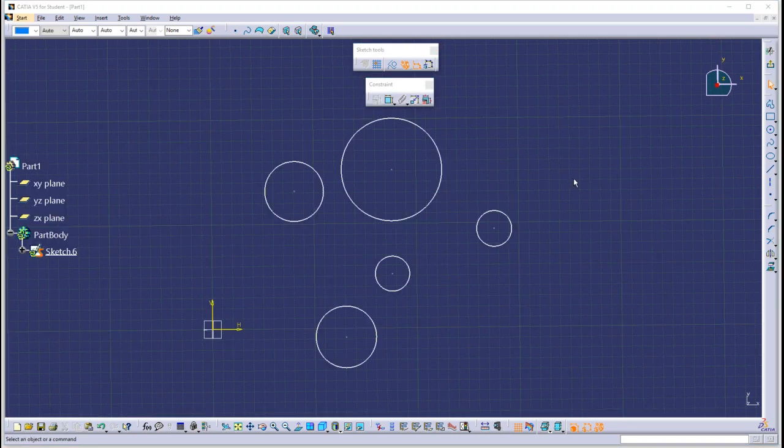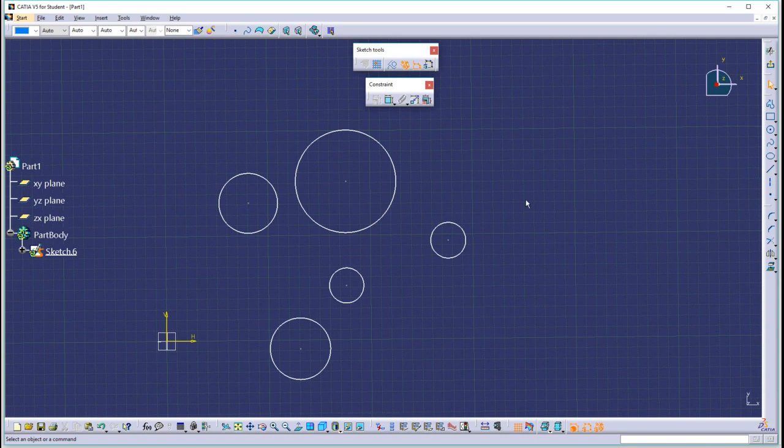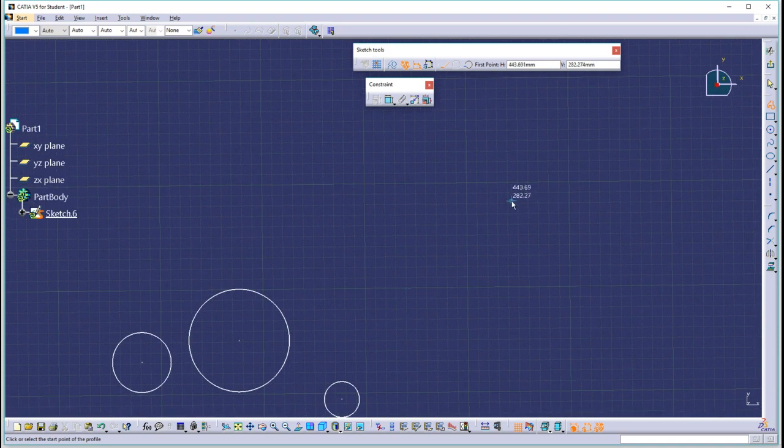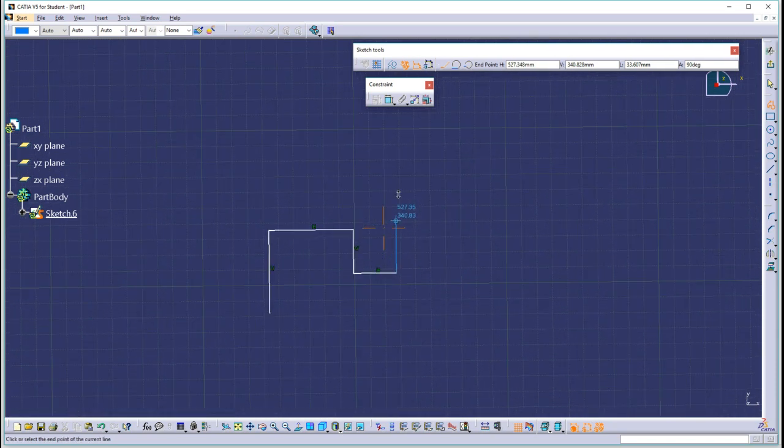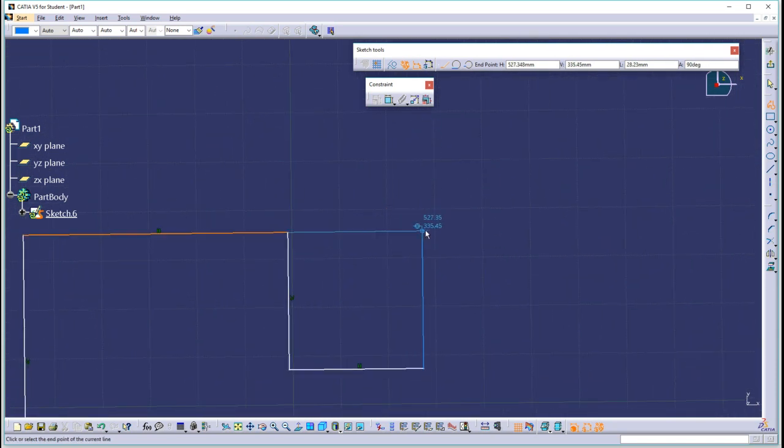Okay, let's wrap up this section on sketcher constraints, telling you how to detect constraints. So notice, let's get up over here. As I draw a line, if it's vertical, it's picking up a vertical constraint and a horizontal, and then I come down to pick up another vertical, horizontal, and then when I come up here, notice the little blue line that's detected. That's picking up a coincidence constraint with that line. So now you notice that little circle that's there.